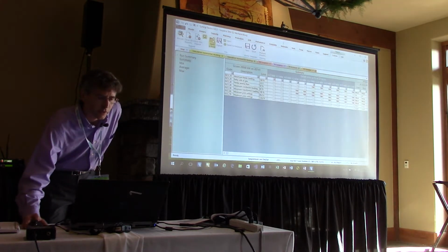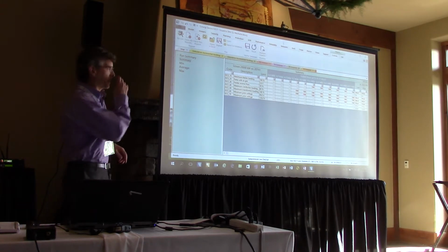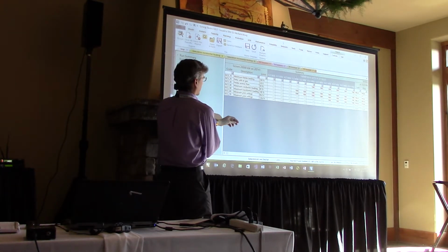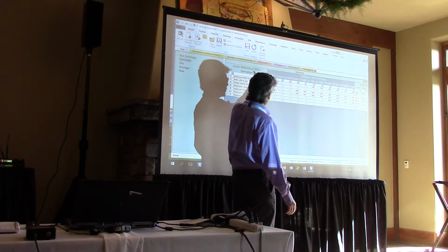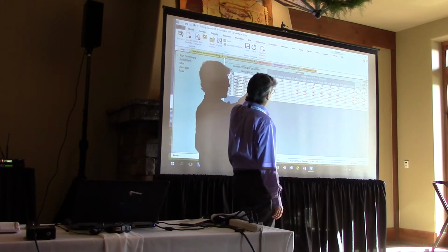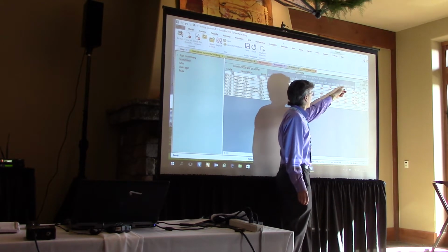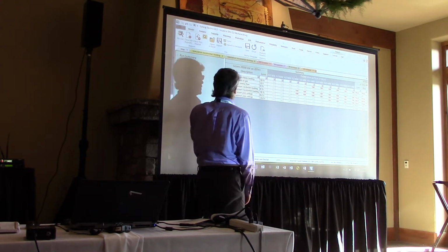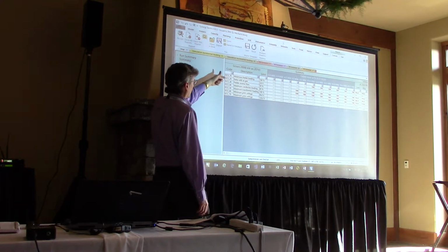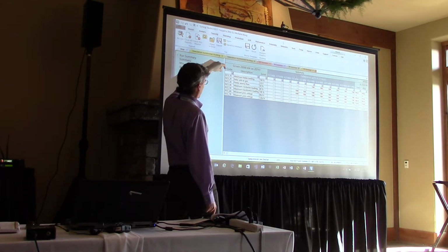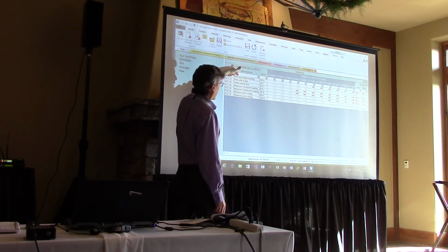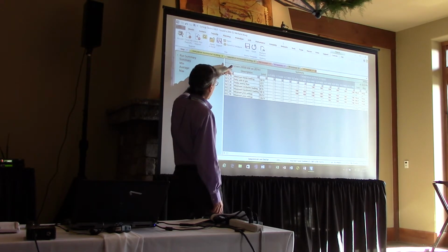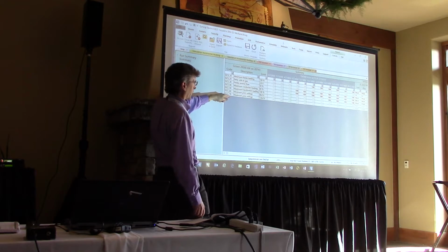And we were talking about this, Don. So this is the application that we have in place. Across the top of the report here, we're starting with nothing. This is the base case. And we're running out to 20 megawatts here. And then these are the screens. We've got some official looking tags on these. This first one is feeder loading. And you can see delta voltage, reverse flow, and so on. So we've got 7 screens in place.